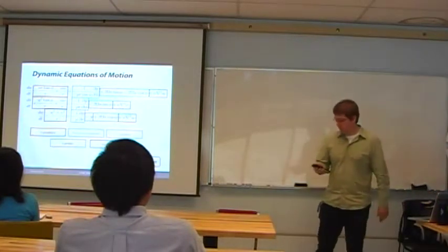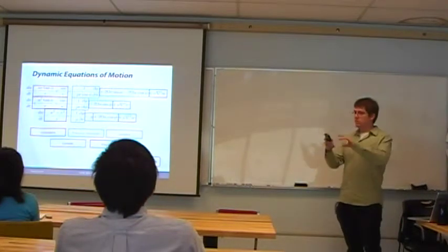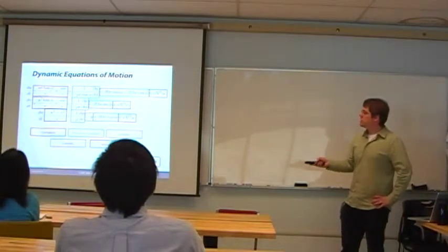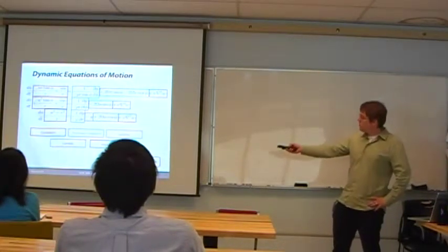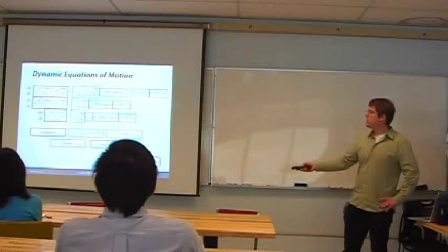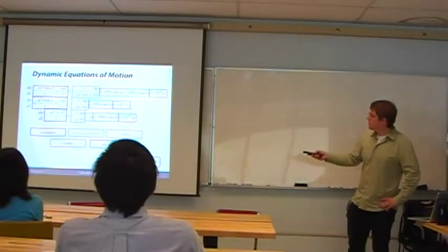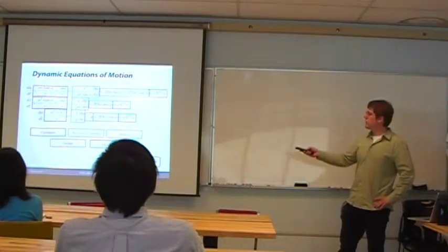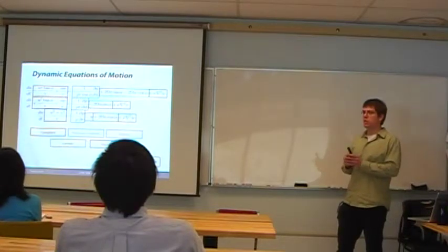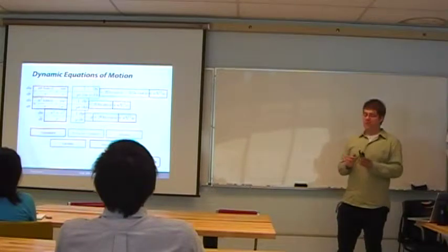The forces that we've derived so far consist of curvature terms, associated with the fact that we're working in a spherical domain. We have pressure gradient forces, here expressed in spherical coordinates. Note that due to the presence of spherical coordinates, that's where we introduce these additional metric terms in the denominator in front of the pressure gradient. We have Coriolis forces, given by the sine Coriolis terms in the U momentum and V momentum equations. These are the ones responsible for deflecting fluid parcels to the right in the northern hemisphere and to the left in the southern hemisphere.